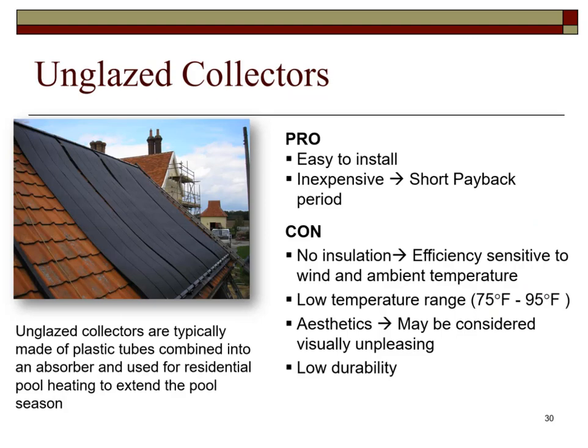The unglazed collector is shown. They are uninsulated because the temperature difference between the water in the collector and the ambient temperature is small. These are the most inefficient type of collectors on the market. However, they are inexpensive and work well heating pools. Most incentive programs do not offer funding for unglazed solar collectors.